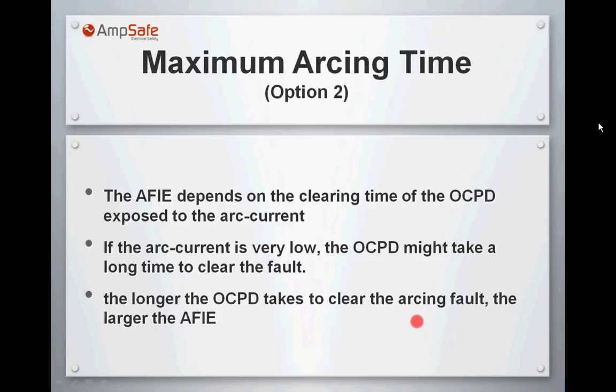But in the real world, when you have an arc flash event, there is a blast and there is a person that is scared. There are two things: a very scared, shocked person, and a person pushed away by a blast. Both things happen at the same time. In an arc flash, the person by intuition is going to be running away from the danger, with his own feet, jumping away, jumping back, protecting himself. And also the blast is going to impel him backwards. It's a big blast. It's like TNT dynamite blowing up inside the panel. So it's going to push him back.